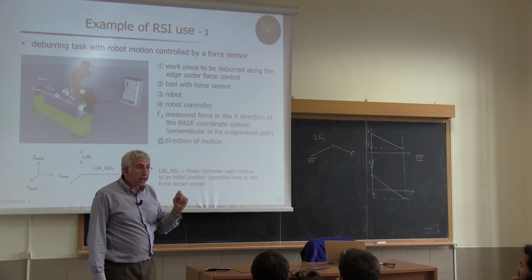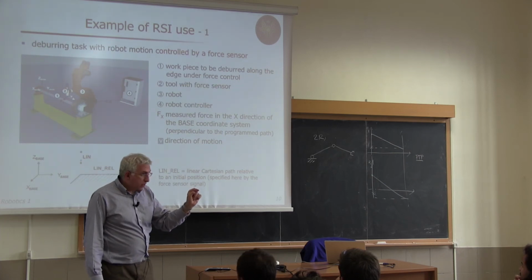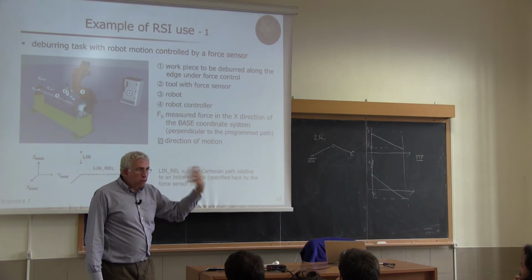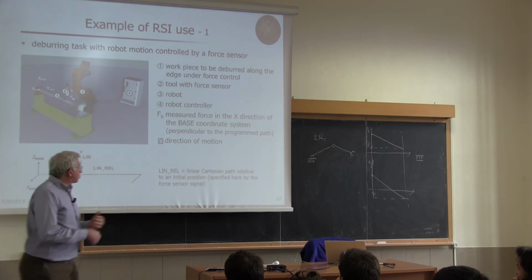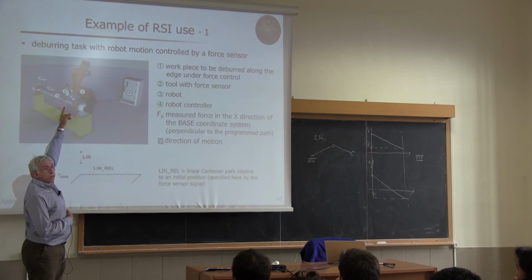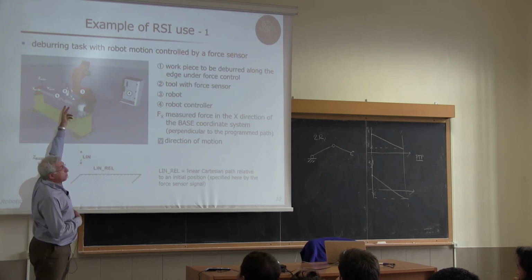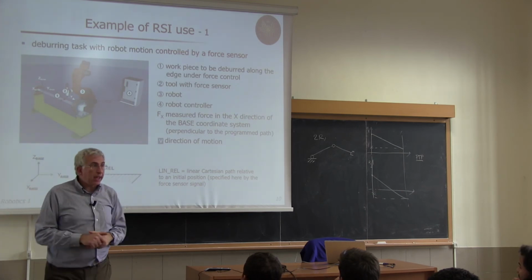The force sensor provides measurement in its own frame. Okay? So if you don't convert this externally, but just throw it in, the controller should know where the sensor is. In fact, there is some frame which moves together with the direct kinematics, then there may be some final offset added.